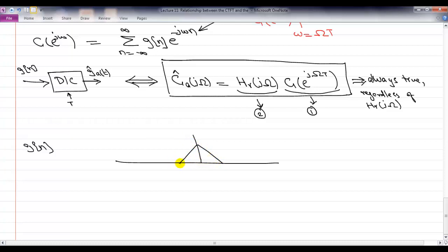Assume this is minus pi and this is pi, and this is some value B. Where this Fourier transform came from, we don't care. You could have just synthesized this thing. You can, for example, use a digital system to synthesize artificial sequences. We don't care where it came from, but it has a Fourier transform, which has to be, of course, periodic, and it keeps on going to minus 2 pi, and so forth.